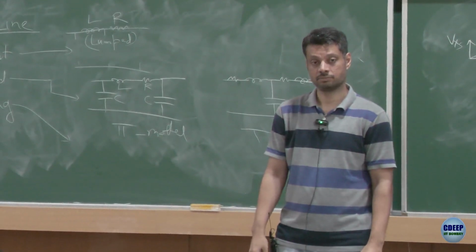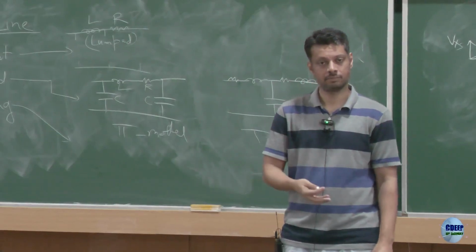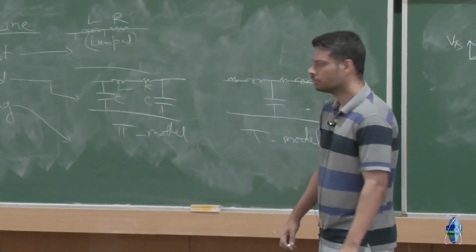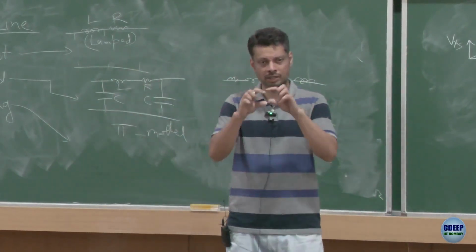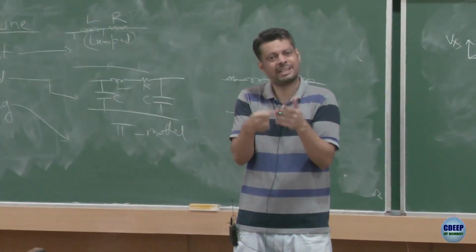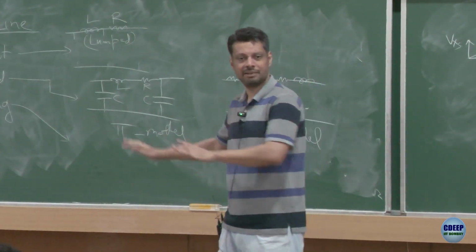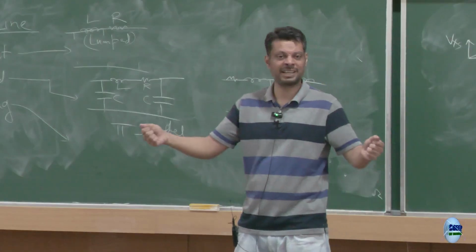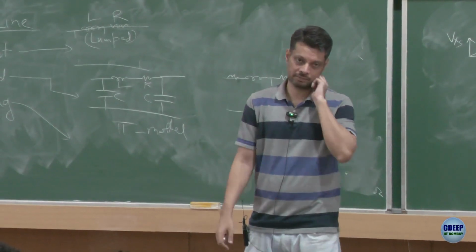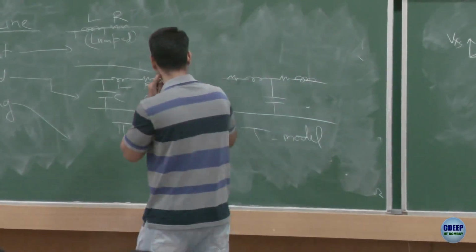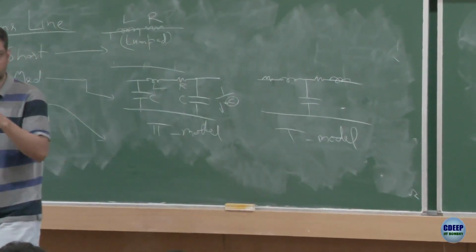Yes, but it's AC, so it's AC. Yeah. So in reality there is one, but because if the distance is so small, the overlapping areas may be so small that the values may not be something which you consider about. That's the only thing. But reality everything is same, right? Just not that if you have made it longer line something has changed. It's only the values are small and therefore you can ignore it. The impedance will be 1 upon j omega c. If c is too small, you can avoid this shunt branch.